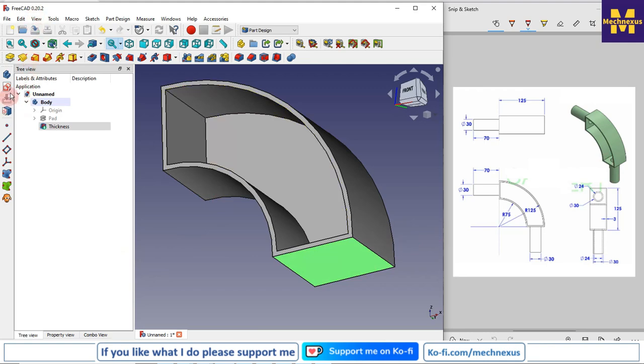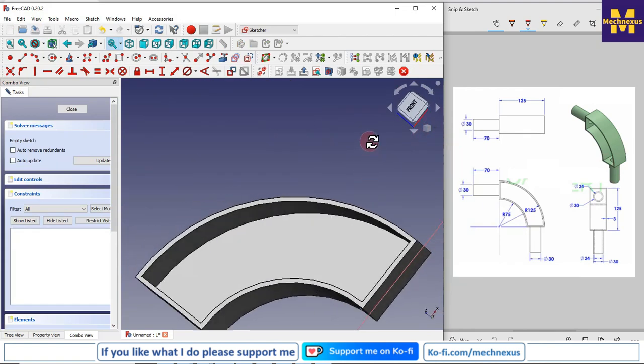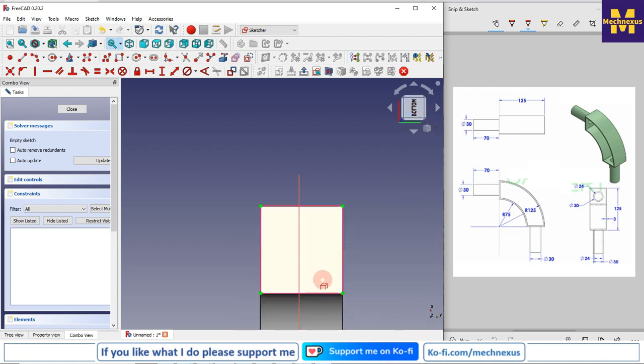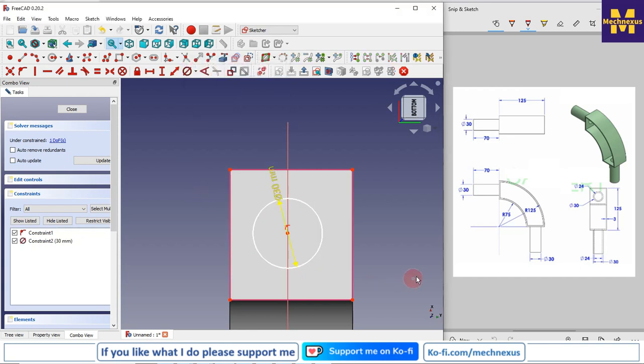Now we will make these pipes. For this I will select this face and I will create a sketch. I will switch to the isometric view and I will project the edges. So I will project all the edges and I will make it to the normal. Now I will create a circle and give it a diameter of 30.